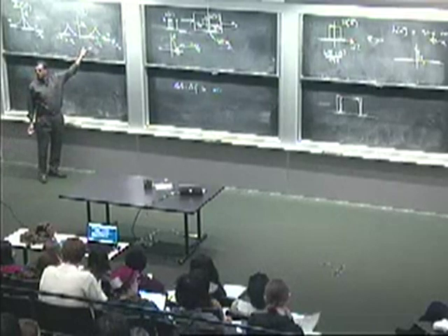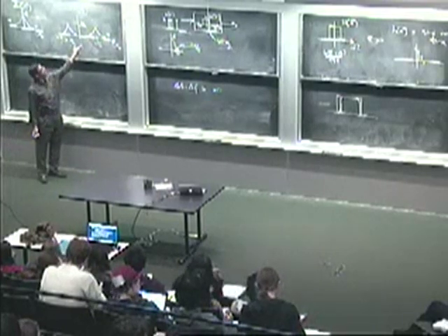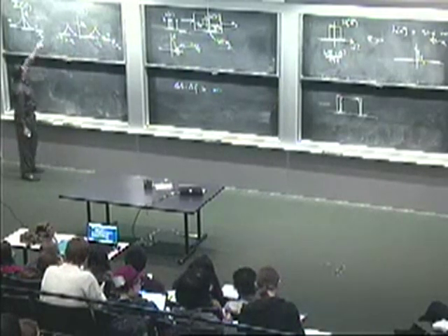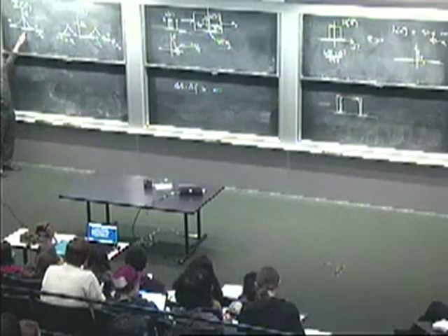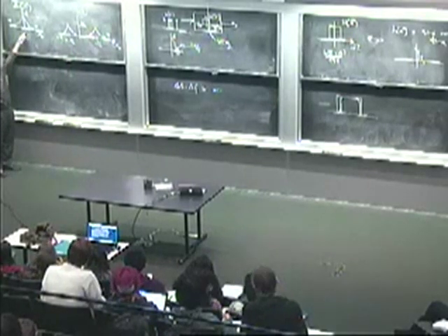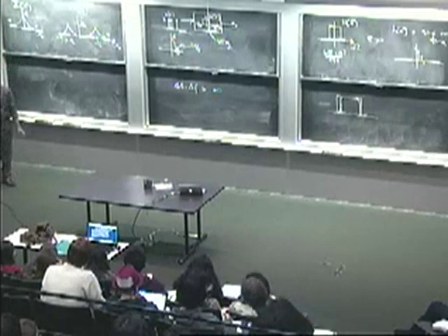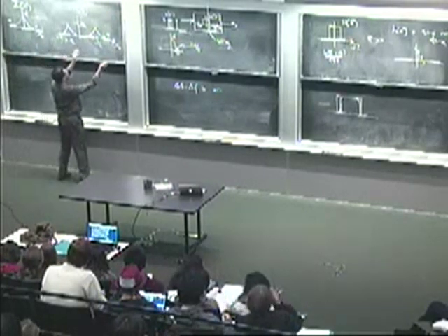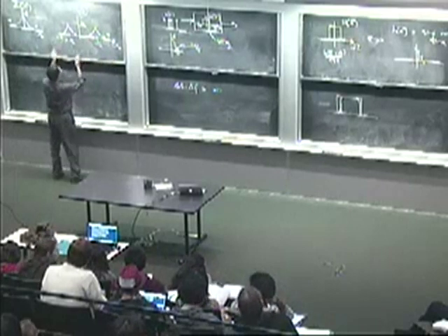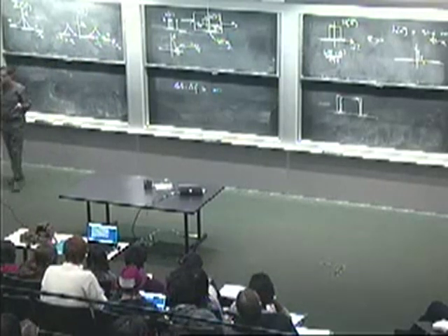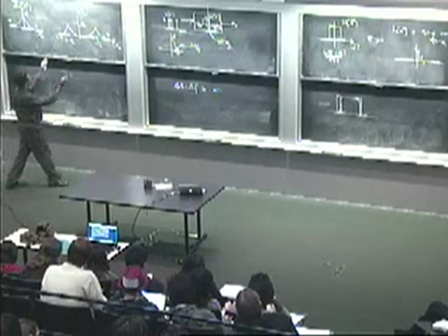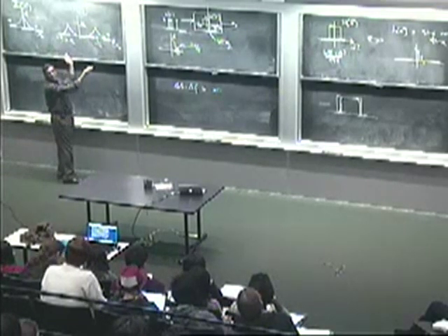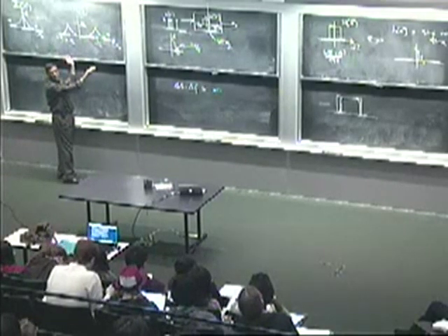This is what's coming in to our receiver, and now we've got to process this to get back a signal that has this spectrum. We've learned a trick, which is modulation. Multiply by a cosine, and you'll take the spectrum and replicate it at omega c and at minus omega c. I'm going to use the same trick again. I'm going to take the received signal multiplied by a cosine at the same carrier frequency.